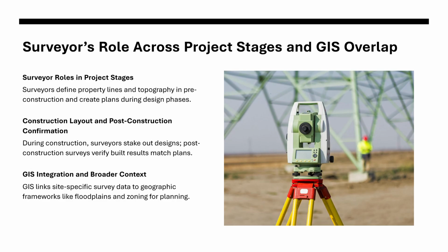And surveyors play a role at multiple stages of the AEC process. During pre-construction, survey data defines the property lines, topography, utilities, and drainage that will set the stage for our design. In the design phase, site survey data is used to generate plans, models, and permits.